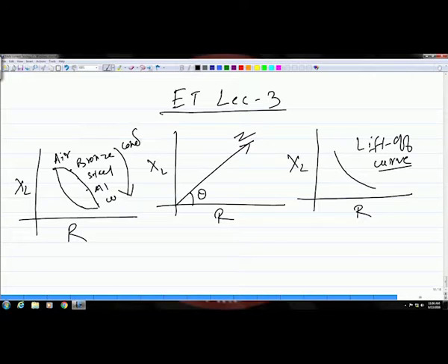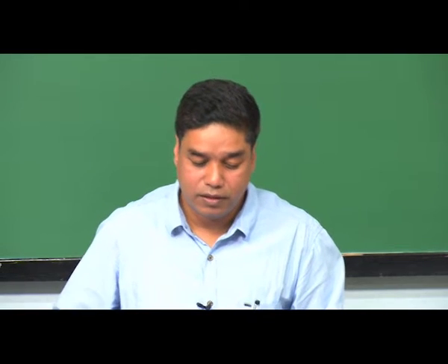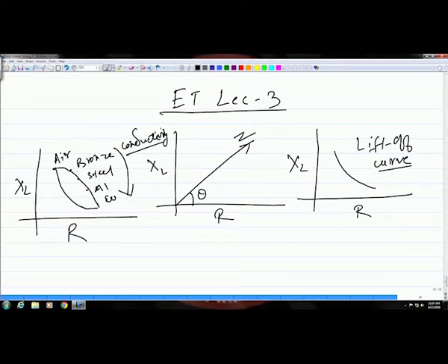So, as you increase the conductivity, you are drawing more and more energy out of the coil, and as a result the increase in the R will be more. So, this conductivity curve is obtained because for different materials the lift off curves will be like this. And if you join the endpoints of them, you get this conductivity curve, okay, as you could see. So, this is the effect of conductivity, that is also we saw.